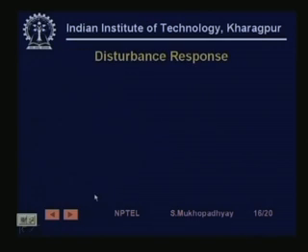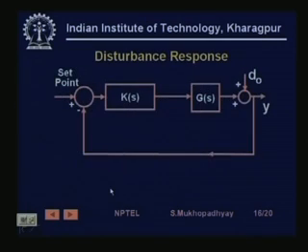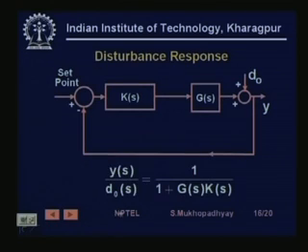Now come to the point of disturbance rejection. So, what is the disturbance response? There are several types of disturbances, and you can do the same kind of analysis, but the most predominant disturbance which generally occurs is the load disturbance in a process, occurring due to various reasons: property variations of materials, variations in power sources, voltages, variations in pressure sources, all sorts of things.